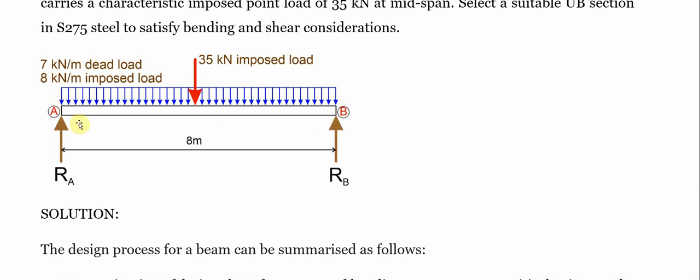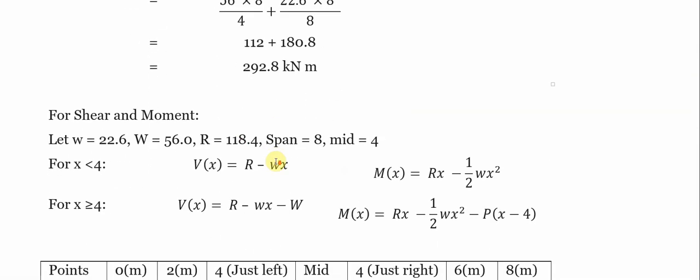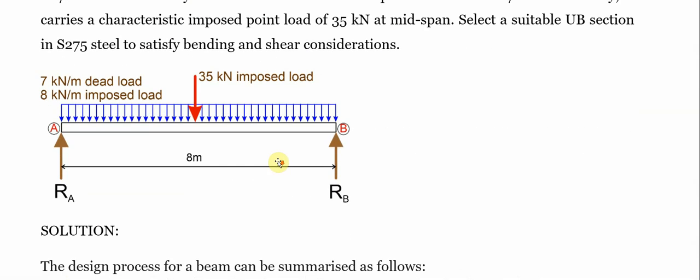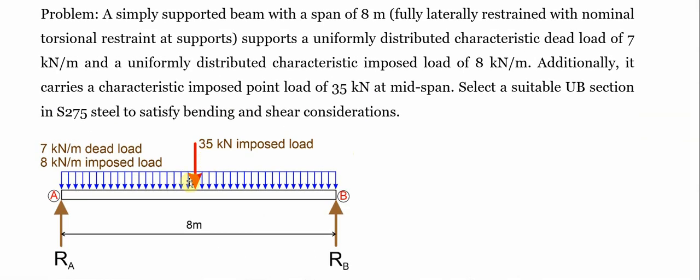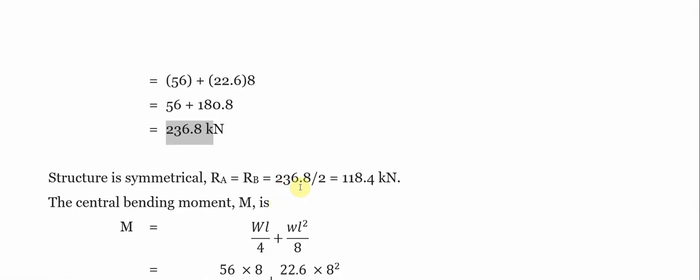Since it only has two supports, we have to know what load each one will carry. Because it is symmetrically loaded, we divide by 2. Had the load been at a distance, we would have to calculate the actual load sent to each support. But since it is at the centroid, we just divide the load by 2 and believe that each support will carry half of the load, which is what we have here.